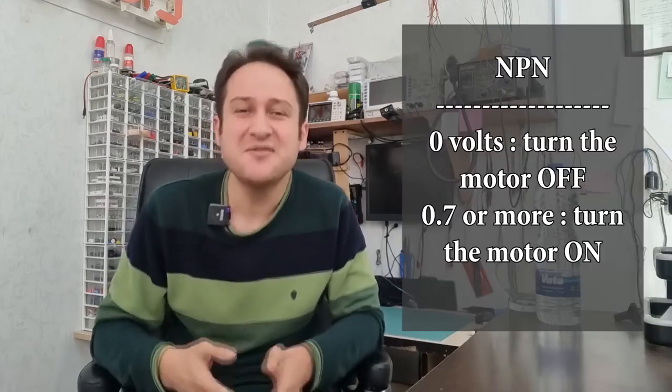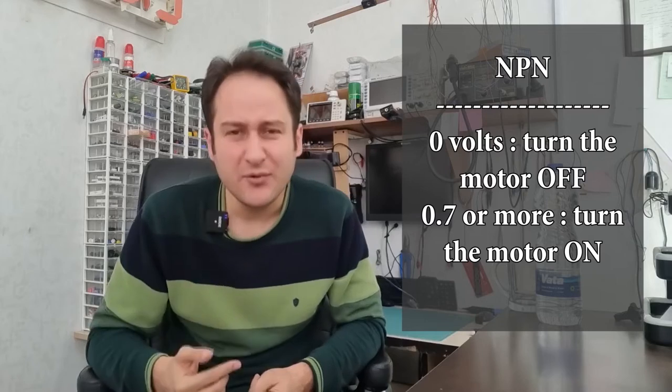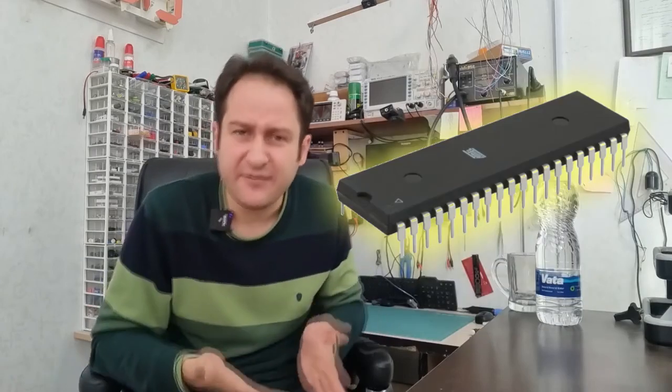With these assumptions, if you try to switch the motor using NPN type transistors, you simply need 0 volts to turn the transistor off and a voltage over 0.7 volts to turn the transistor on, which is available on every I/O pin on any microcontroller.